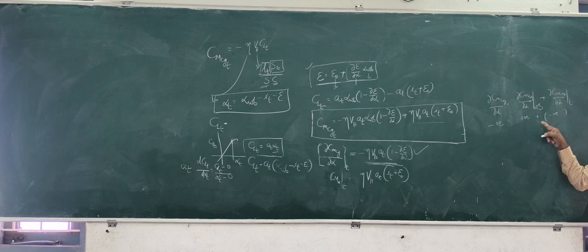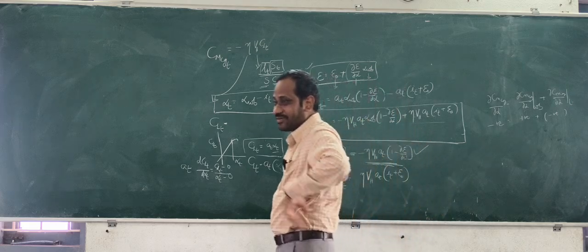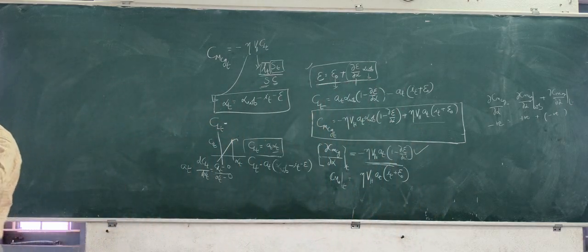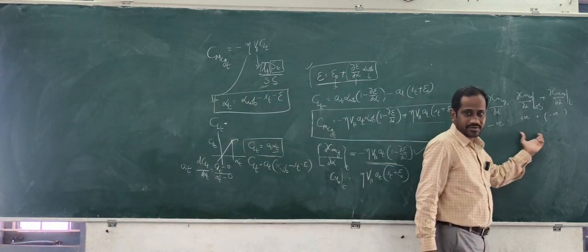This value, which value should be larger to make the summation negative? This value should be a larger value. Like that, that is the design process to make the aeroplane possess longitudinal static stability. That is the contribution of the tail. So, tail design is essential to make the aircraft longitudinally stable. So, look at this, this is the idea of aircraft design. Did you get the point?